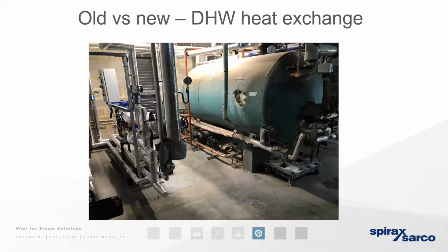And remember, if we're condensing steam at a higher pressure, there's nowhere near as much energy contained within it as there is with steam at a lower pressure. So the process time is going to extend and we get a greater energy inefficiency. But another factor to consider when we're condensing steam at a higher pressure is the fact that we're far more likely to get an insulating film of scale being produced.